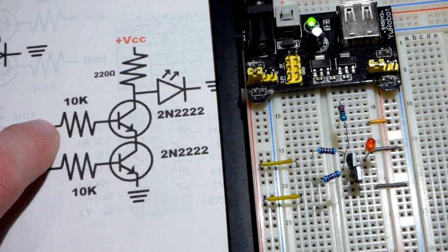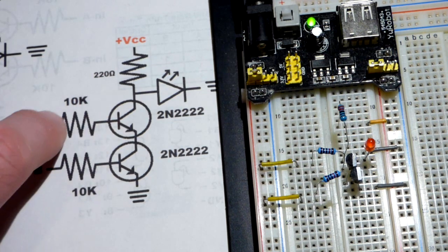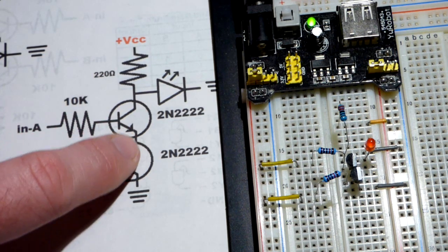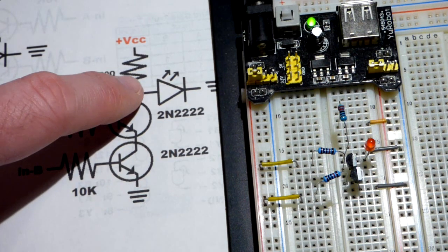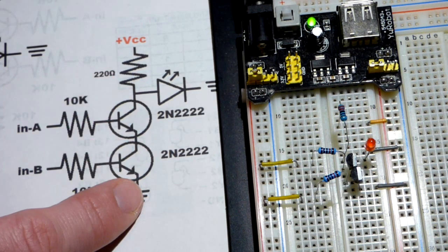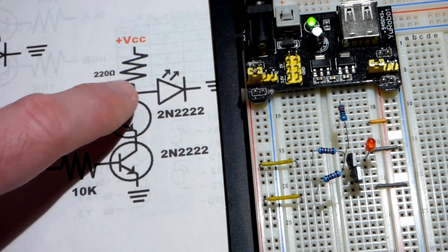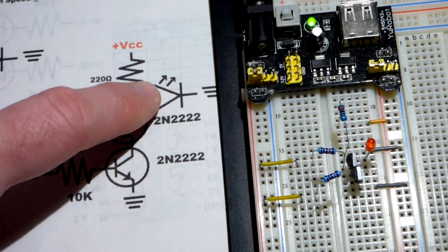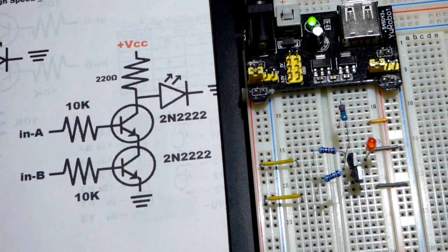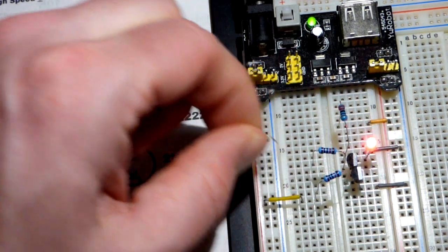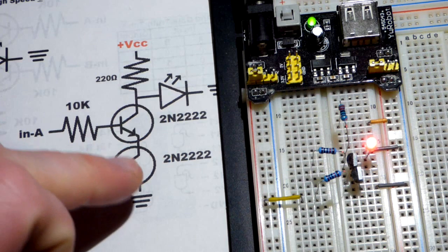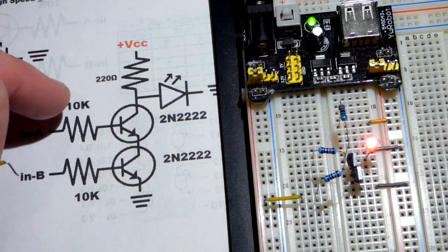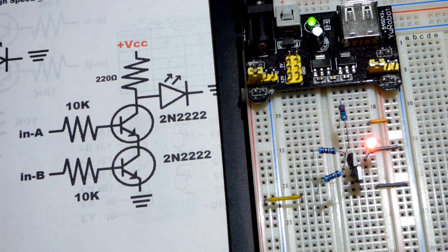And then once it does, the current through this base to emitter now has a path through the transistor, which also allows this one to fully conduct. So they're both fully conducting, so it's an easier path from this point to ground than going through the LED, just like the switches. But of course, if we remove either one of them, that will cut off the path, either one or both of them, and it's on. So we have a fairly practical NAND gate here.